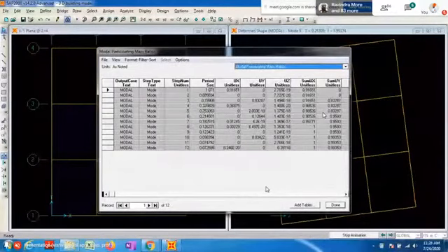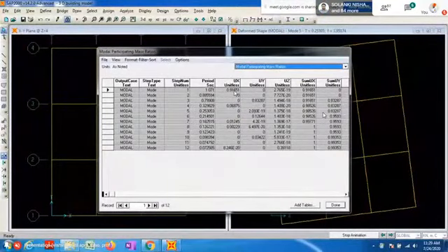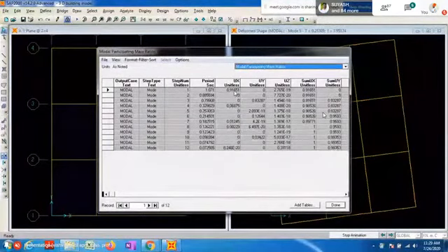This is the first mode. What is the time period? 1.01. What is the participation? It is 91. 90 percent has been excited in the first mode. Therefore, the structure is a first mode dominated structure along the X direction. Then what about the second mode? In the second mode, mass participation is 0, 0. But it is a torsional mode. It indicates it is torsional.